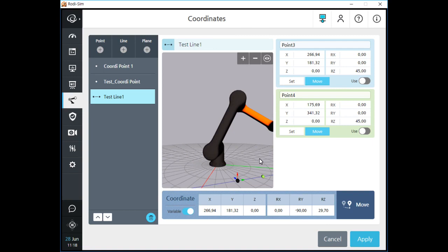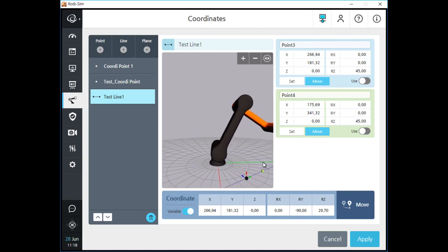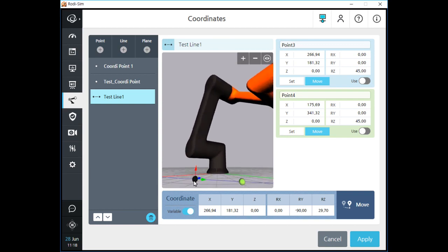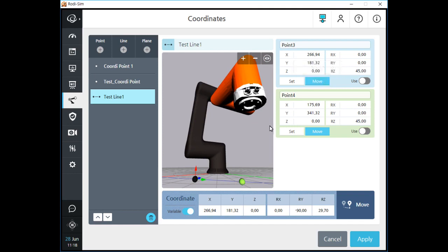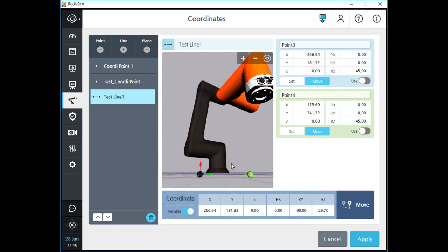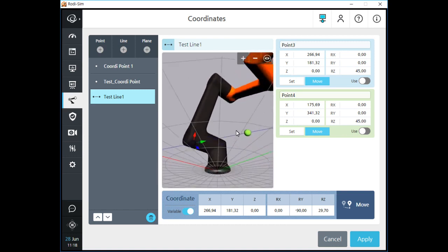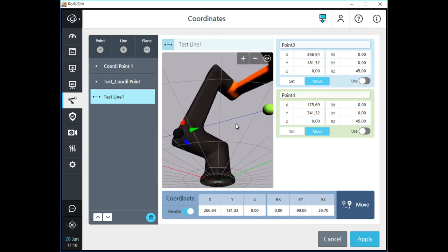After you click the OK button this time, you can see your new y-axis on the screen in blue color. The black sphere is the origin of this coordinate and the positive direction of the y-axis is the same as the direction from the first to the second waypoint. In this line type coordinate, it's hard to get a precise x and y axis as you want, so I recommend you use this type when you need a specific direction. I usually use this line type coordinate for manual control mode, not for modifying the move commands to copy and paste.